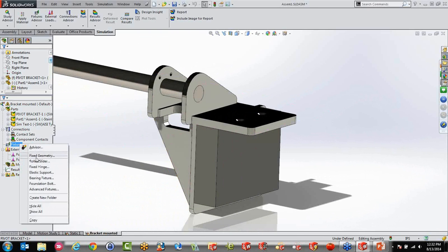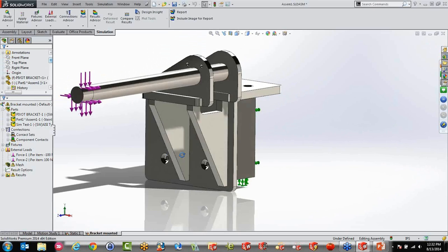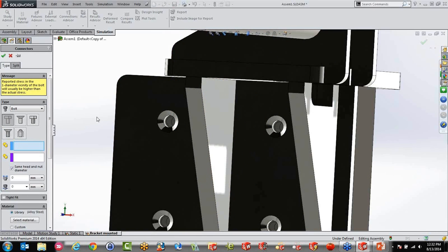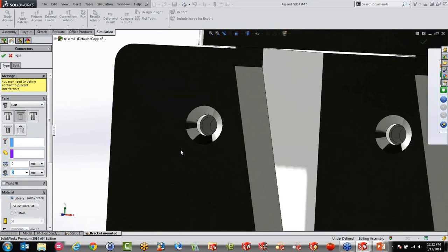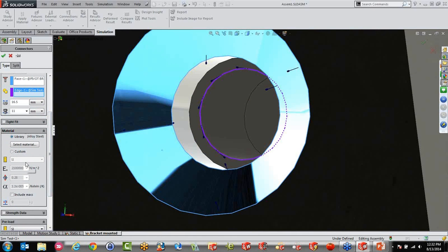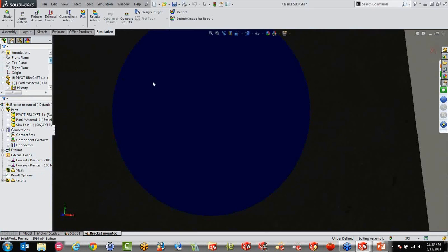So if I instead fix this part, say this thing is fixed, now I can go into SolidWorks and say I want you to add a bolt, one of these bolts here, and I can select this. And if I select these, the hole wizard hole is smart enough to know the size. Now I can tell you exactly how this part's going to react with the bolts, because that's different when it's mounted like this. We can even add some torque to these bolts if we wanted.